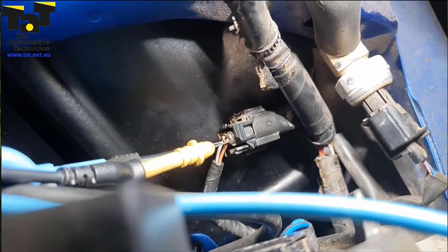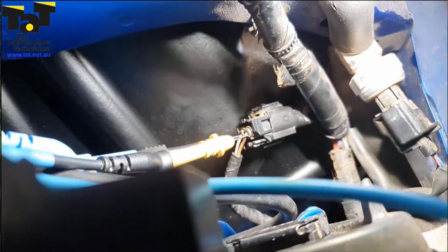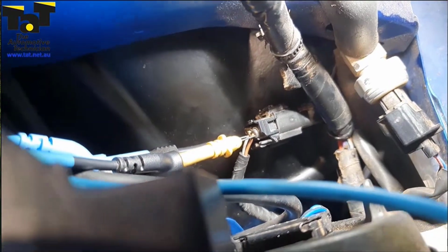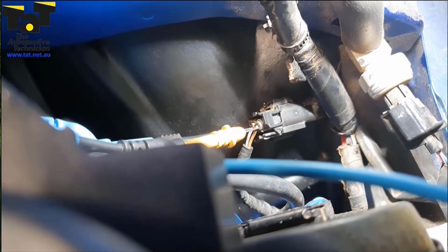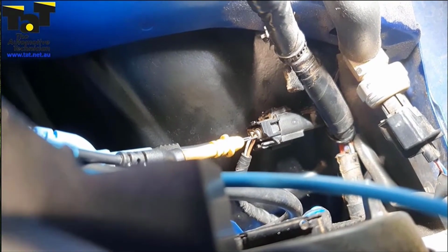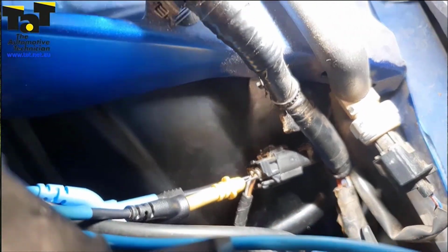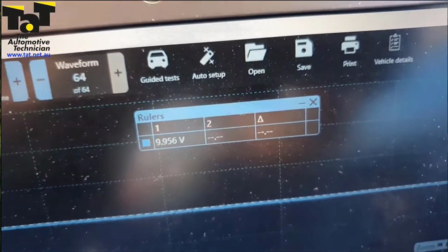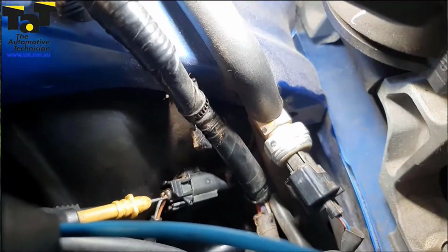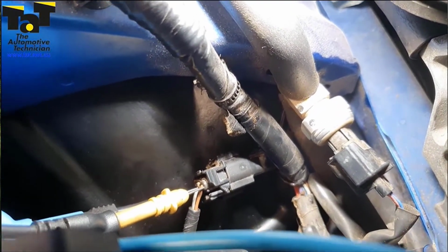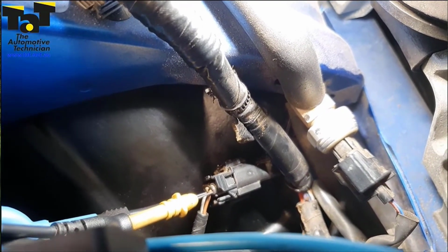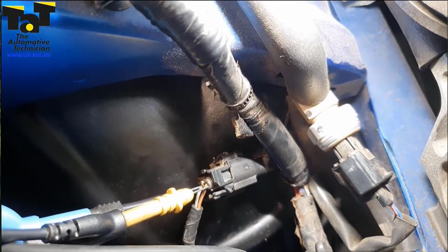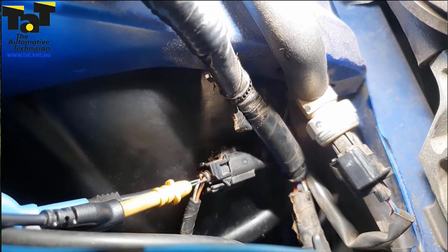So stay with us. Firstly, what I want you to look at is the state of that connector. We probed these two wires, and being a magneto resistive active type wheel speed sensor, we needed to make sure that we had power on one side and ground on the other side. On the vehicle side we do have that, as you can see, 10 volts. But on the other side of the sensor there was no battery feed from the actual vehicle side, and the reason why is this connector was damaged and the terminal tension was too great and it was not touching properly.